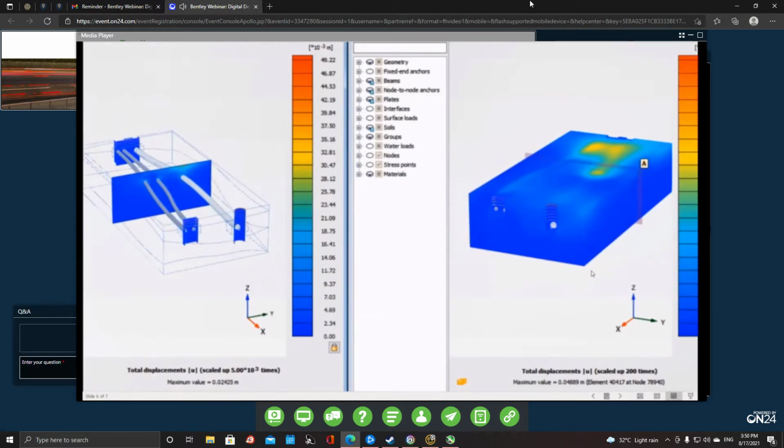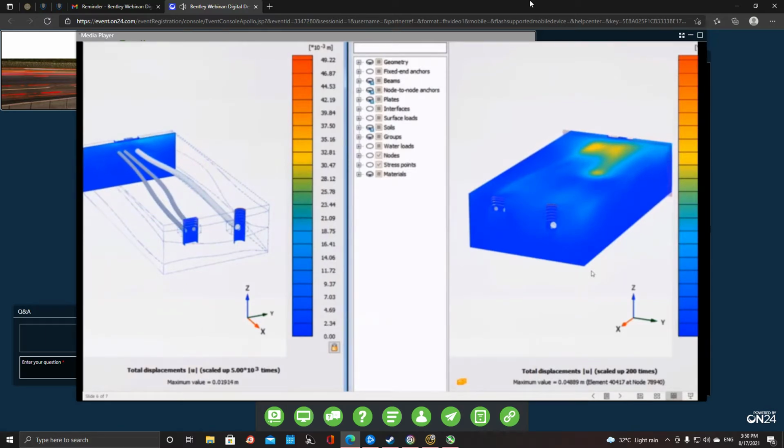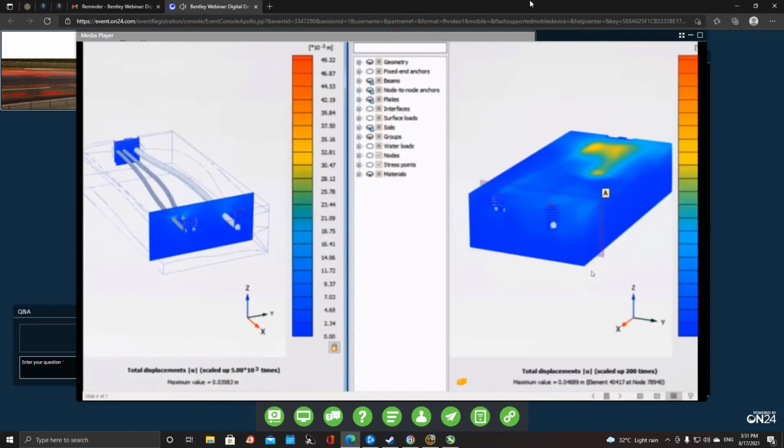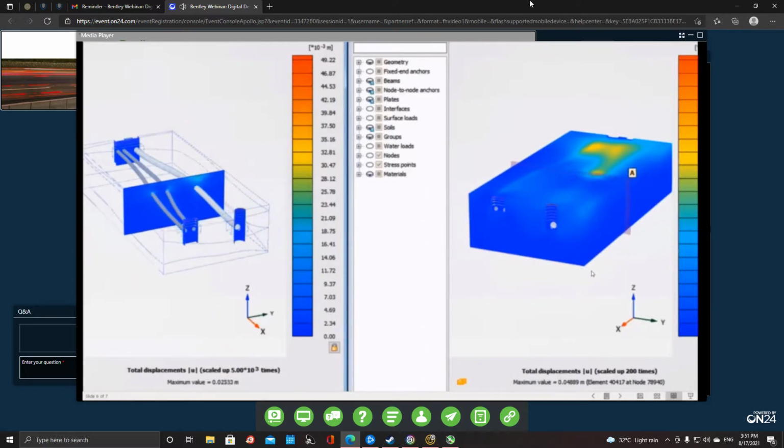In most of the cases, tunneling design in terms of geometry, alignment, and support pressure are governed by the serviceability criteria in order to minimize the impact on the existing infrastructures. With modern TBM technology nowadays, it is not difficult to control the volume loss within 3%, even for poor ground condition.